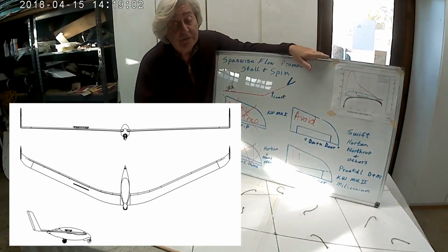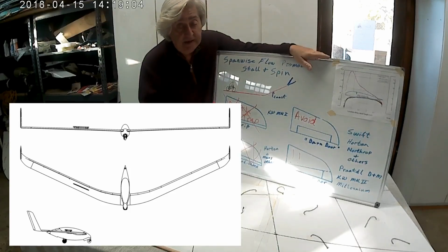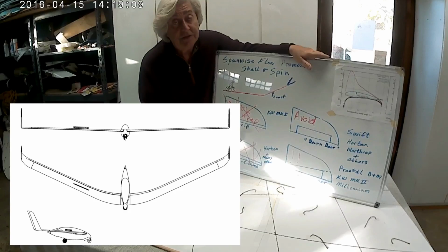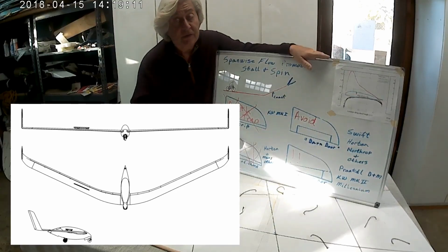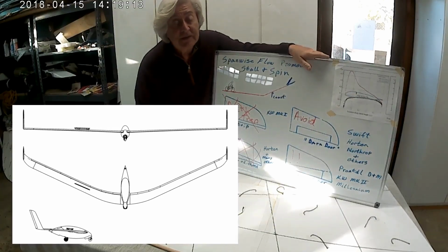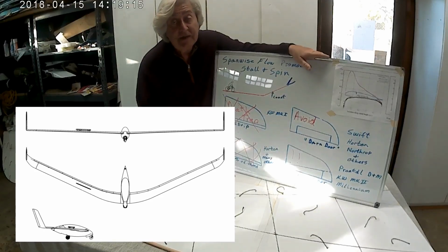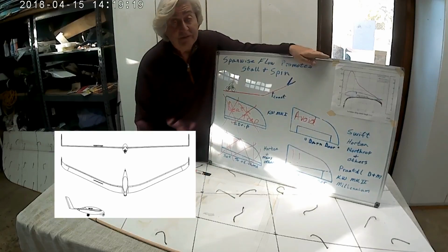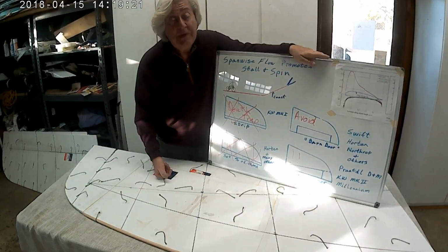And I have very serious concerns for them. Even with the laminar flow airfoil, we're getting the higher momentum flow closer to the trailing edge. I think it's still going to be an issue. And I know that they've already built their wings, they've got controls in there and everything. They've flown a half-scale model, but once again, the model is not going to tell you the truth. And I would have to just give a shout out to them, be extremely careful with a full-size one.